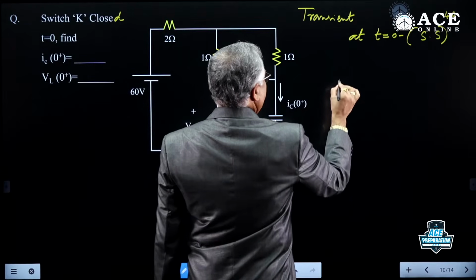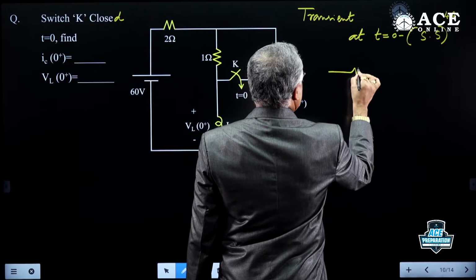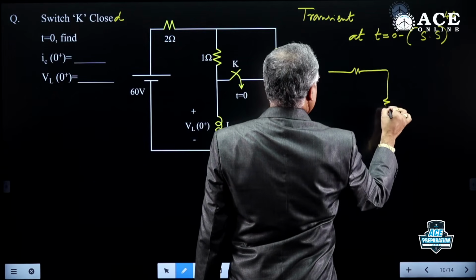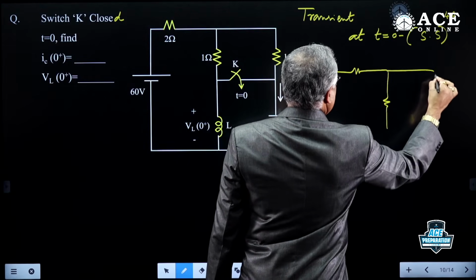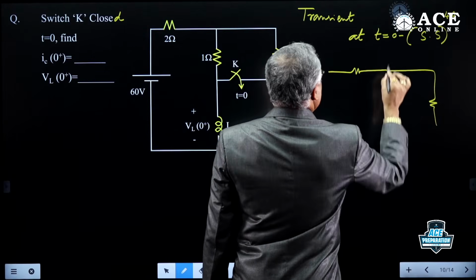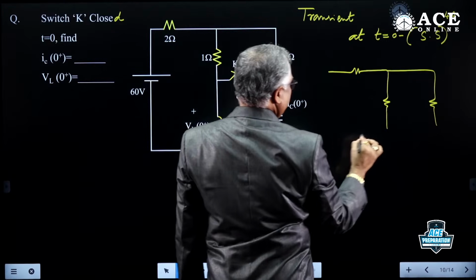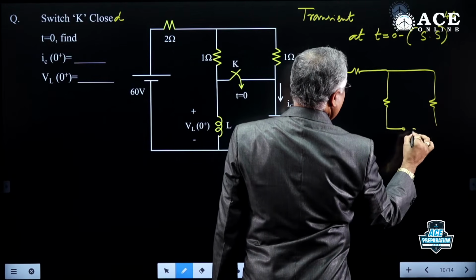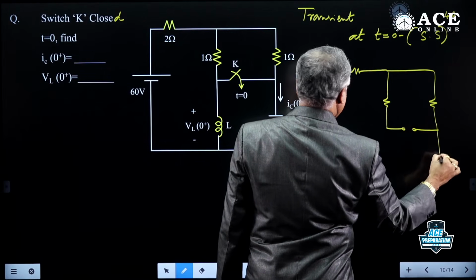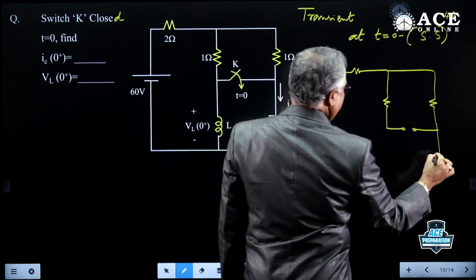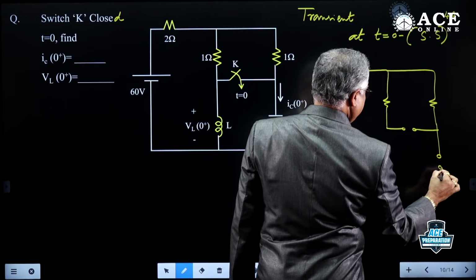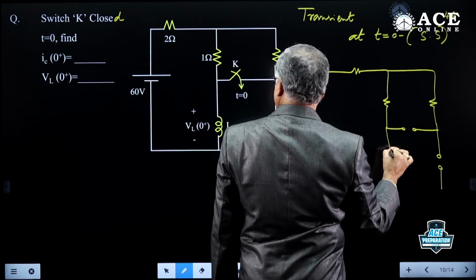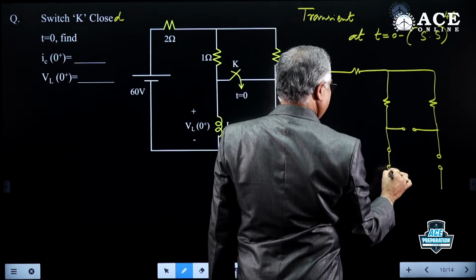So under that condition, at 0 minus, the switch is open. The capacitor is open in the steady state. The inductor is short.